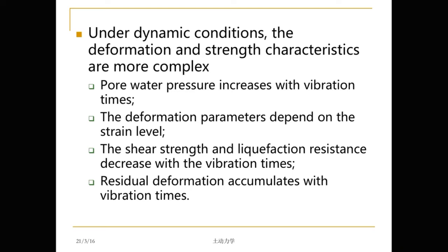The first is that pore water pressure increases with vibration times. We know that during an earthquake, if it is a saturated loose zone, we will observe that the pore water pressure will increase with the shaking.